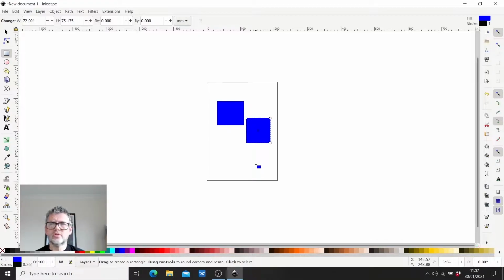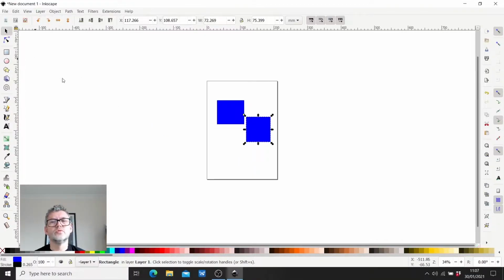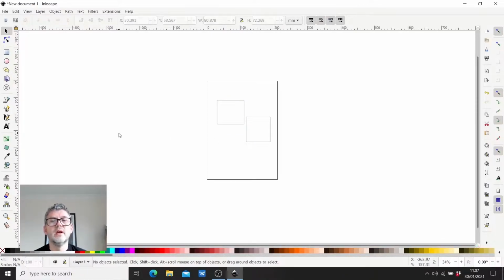And if you look on a lot of tutorials, they'll tell you to highlight it and then just go down to the bottom colors here and make it white. And you could do the same with this one as well. Go down here and make it white. And what I found though is that when we move our object over another one and click off there, you can see it actually overlaps the other one. And what we've done is we've created layers, which gets complicated for CAD drawings. I can highlight this one and just show you what I mean.